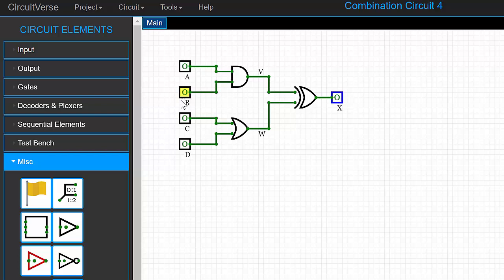So you've got all your combinations, and in your workbook you'll have the 16 possibilities that you can get from these 4 different switches. And then what we've got to do is basically work through and put in our options and see what would happen here. So an exclusive, an OR here, bang from there, that turns that on. We turn that off and click that one on, same result. Press them both on, still getting a 1.